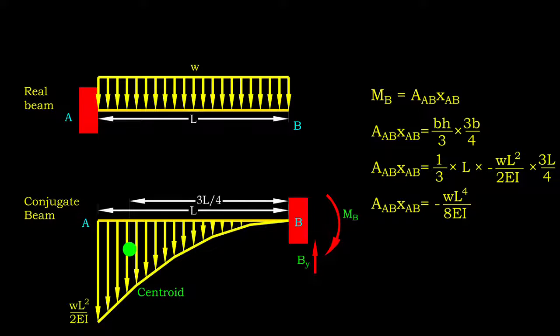Bending moment, on the other hand, can be determined by determining the product of total loading and lever arm from the fixed end to the centroid of loading. For parabolic spandrel, the centroid is 1/4 base length away from the vertical edge. Therefore, the lever arm from the centroid of loading to the fixed end is 3/4 L. We are now able to calculate the resultant bending moment at fixed end.